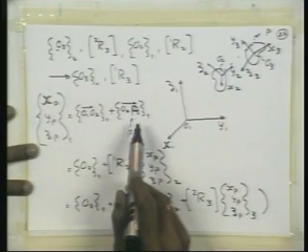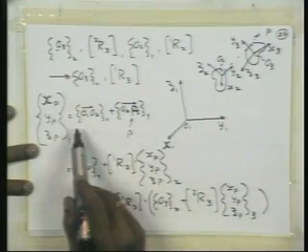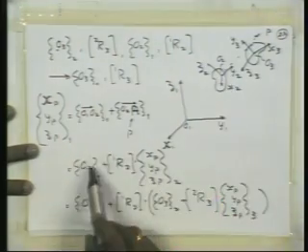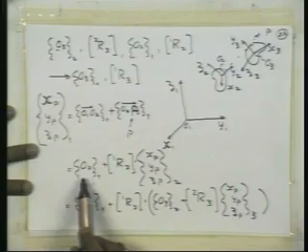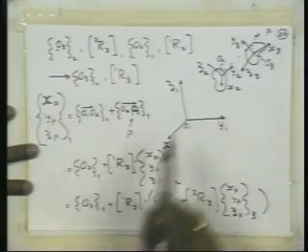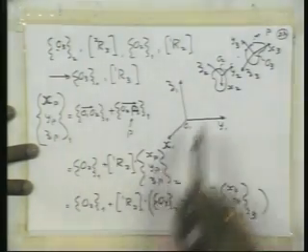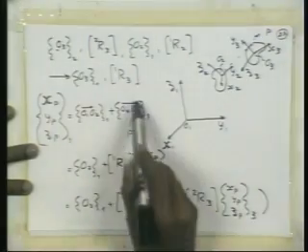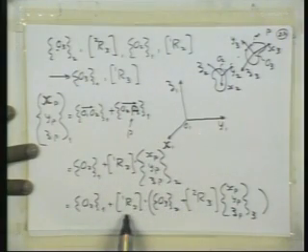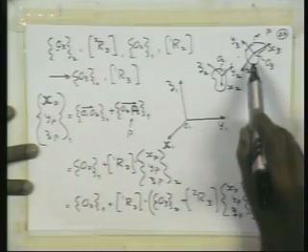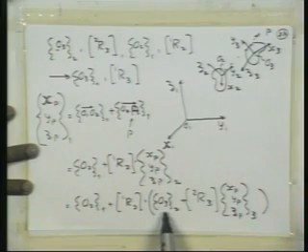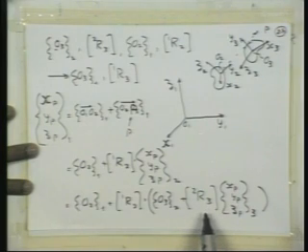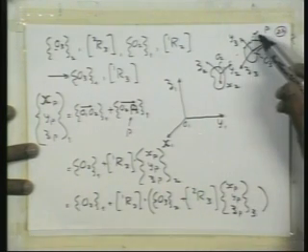This is O2 in 1, that is this particular vector, plus R2 with respect to 1, that is R of 2 with respect to 1, into the coordinates of this point in the second rigid body, and then this particular thing we expanded further in this form. That is the origin of the third rigid body with respect to the second, plus the rotation matrix of 3 with respect to 2, multiplied by the local coordinates of P in 3.